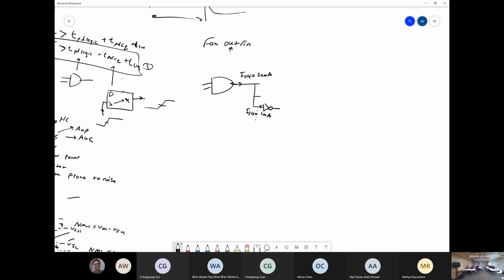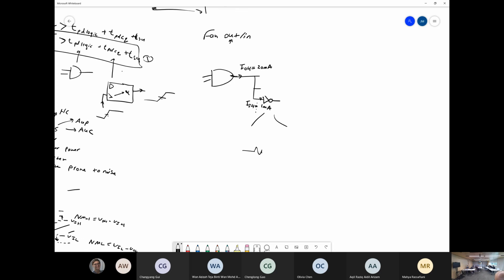Now, there is something more complicated when it comes to propagation delays. Inside these gates, equivalently, your input to your gate will look like this, electrically. There won't be physical components like this, might be, but it can be boiled down to an equivalent of this, right? An RC low pass or an RC network.